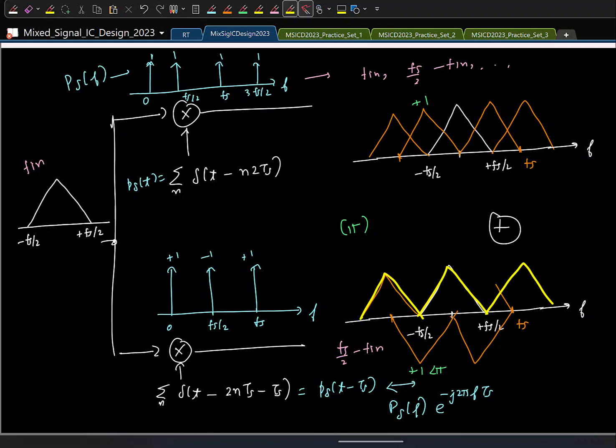N minus 1, right? Because remember that in the n-channel case, each ADC will be sampling at what frequency if the total rate is fs? fs by n. So we'll have images around multiples of fs by n. So we'll have around DC, that is the main spectrum, no issues. Around fs by n, around 2fs by n, and so on. So we'll have a total of n minus 1 images within 0 to fs by 2.